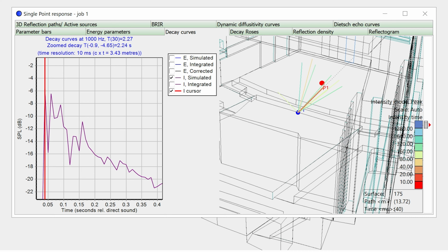You can navigate through intensity peaks with the P and Shift P shortcuts. If you would like to look at individual peaks in the hedgehog, you can hide the rest of the peaks with the H key. There are other ways to adjust the plot.